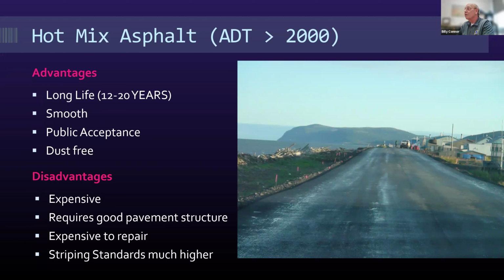One of the disadvantages of that is, of course, it's expensive. It requires a good pavement structure. So that's sometimes where a lot of the cost comes in. You usually have to make a stronger road than you would perhaps use as a gravel road, expensive repair, and usually want striping.